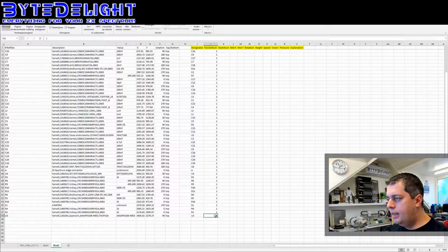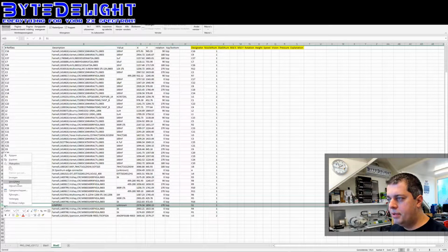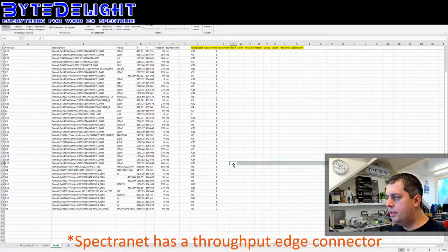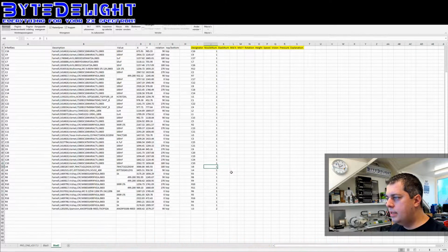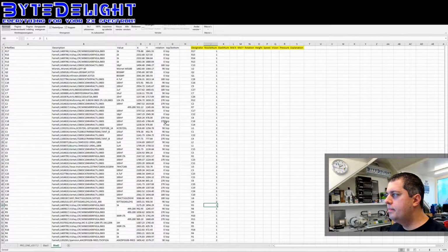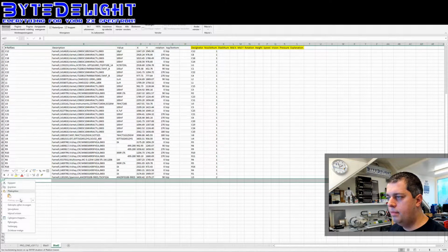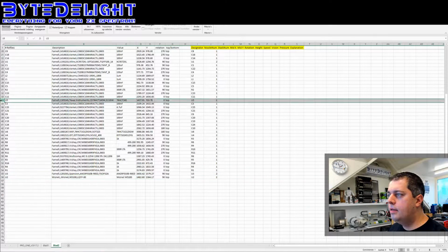So then we have the ROM chip here, which is a bigger one. We have a jumper. We don't need a jumper, so let's get rid of that. Why do I have another edge connector here? I hope I'm not deleting too much at the moment. We'll check it out later on. This is a single gate logic chip, so it's very small as well. Will be picked up by the first nozzle. We got the SRAM chip, and I think this is about the big ones. Maybe it's good to put all the big chips to the bottom of the list. Why not?